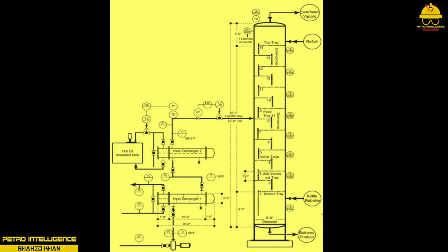All raw materials entering a tower are converted into products. Material balance theory states that the sum of the raw materials entering must equal the total of the products leaving the distillation tower. Column loading is another term associated with material balance. It is defined as the amount of material fed continuously into a distillation column. Heat balance states that the heat that goes into a distillation column must be equal to the heat that goes out of it. Maintaining this balance is critical to the proper functioning of the tower.